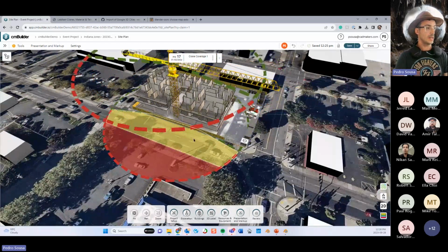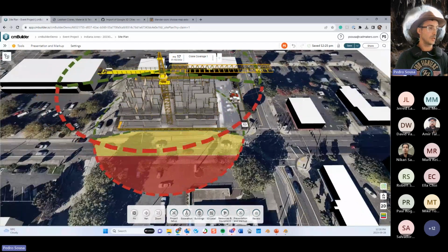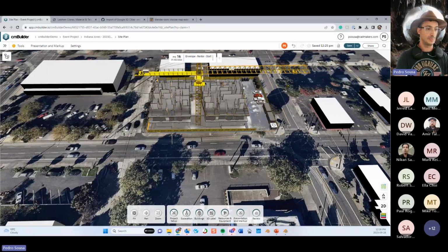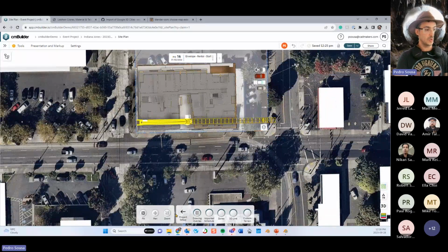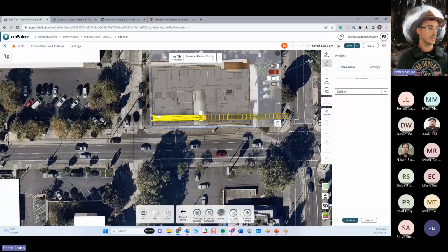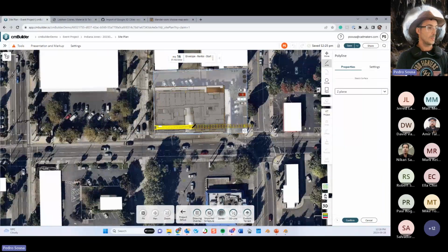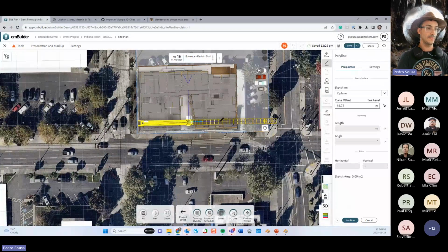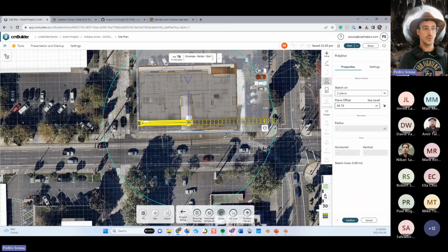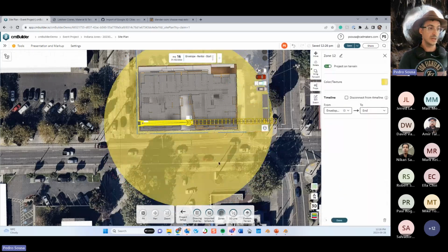Cool. So basically what I did over here, I can redo it again on the previous milestone. The idea is that you're going to use either the 3D lines or the zones, and I'm going to use zones over here just because it's a little bit simpler. So everything will be tied into the center of your crane, and then you can create a circle, right? Where you can click on the center of your crane and then bring that into whatever is the length, the radius that you want to show over here. When you hit confirm, that's going to be created, right?